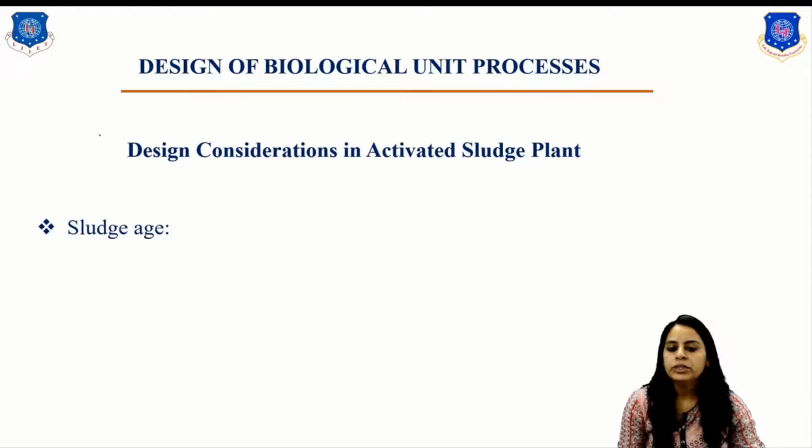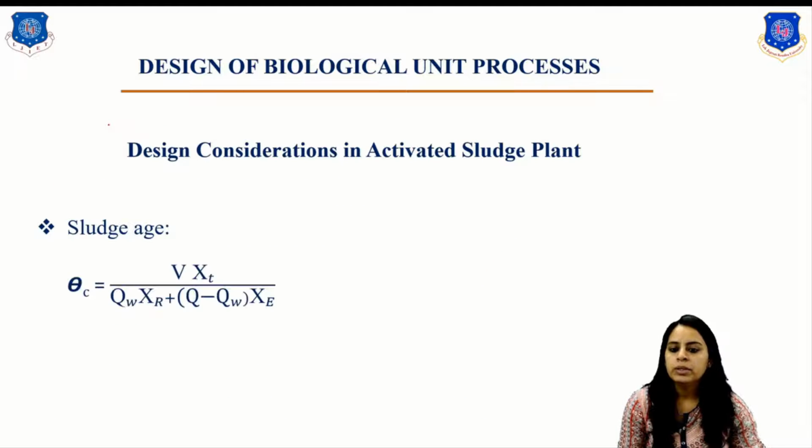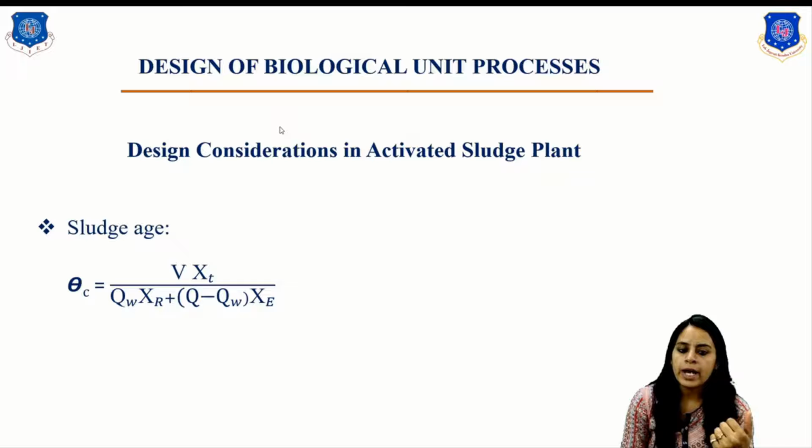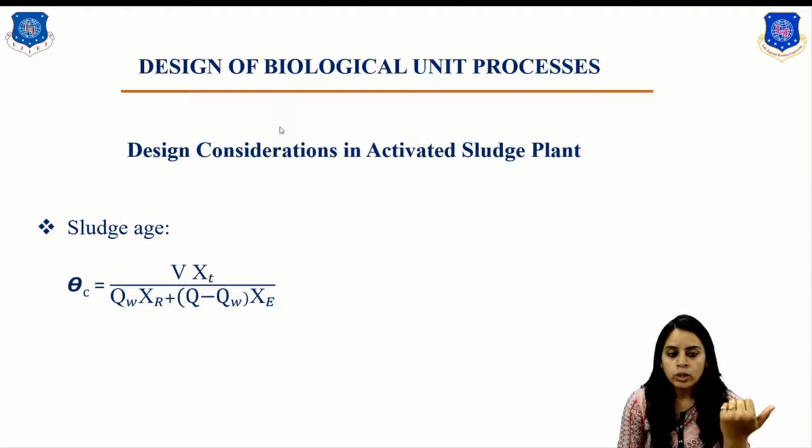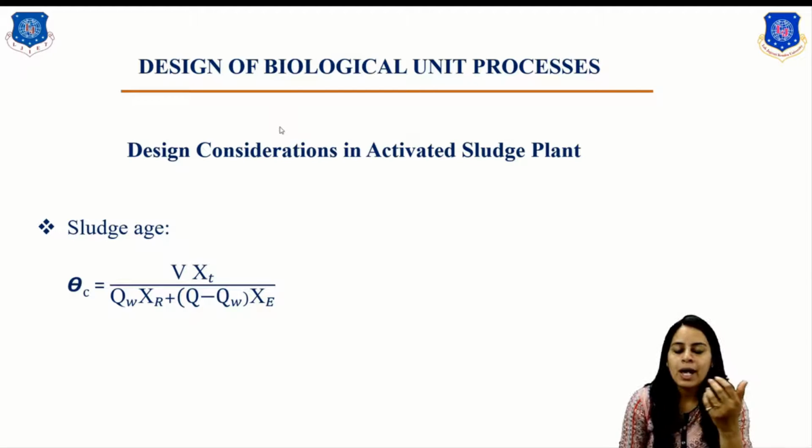Now the next one, the sludge age. It is defined as the average time for which a particle of suspended solid remains under aeration, right? It indicates the residence time of the biological solids in the system. The aeration period is shorter, that is 3 to 30 hours, but the residence time of the biological solids is more than the aeration period and is measured in days. Solids are recycled and hence their residence time is more, right?